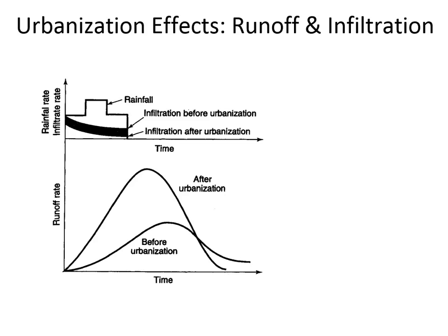And so in the comparison of before urbanization and after urbanization, before urbanization, it takes a long time for the flow rate to go to the peak. And so relatively longer than after urbanization. If you look at after urbanization, the peak occurs sooner. So there's a reduced time to peak, and also the peak is much higher after urbanization.